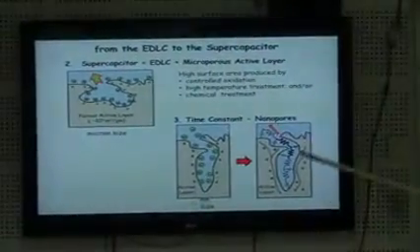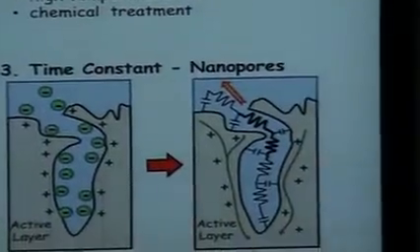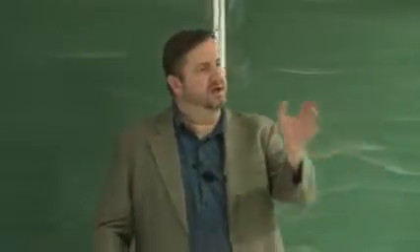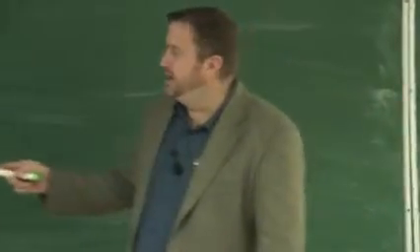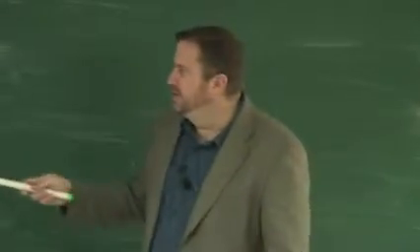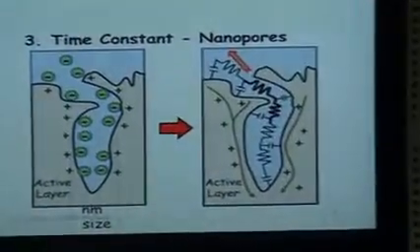I'll give an entire lecture about thermal effects in these devices. But what you can do when you do have nanopores is you could make a transmission line type of model where you have a sequence of resistors and capacitors that represent that process of charge flow into a pore. And in that case, you have not only just these two capacitors inside of an overall capacitor that I talked about before, but you have small effective capacitors along the wall of your porosity.